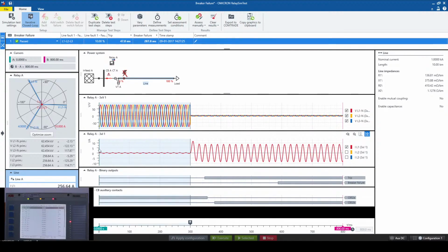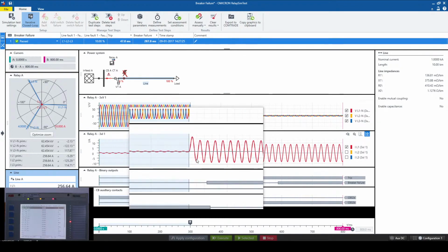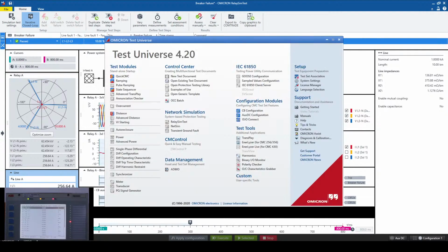So if I want to prove that from a normal working condition that we can see over here, the change in current because of the fault was very abrupt, that could be easily simulated or done using your state sequencer. But if I want to vary my parameters in a smoother and slower way, either to determine what should be the pickup or the drop off of a particular protection function, then we use the ramp function.